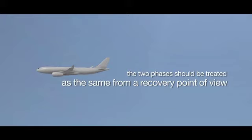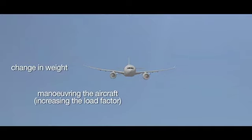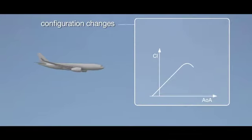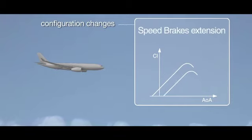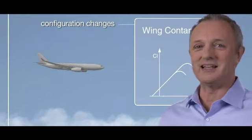Factors that affect the stall speed are change in weight, maneuvering the aircraft increasing the load factor, and configuration changes. This is how the CL versus angle of attack changes with slats extension, flaps extension, speed brakes extension, and finally wing contamination. Let's see how the CL max varies with the Mach.